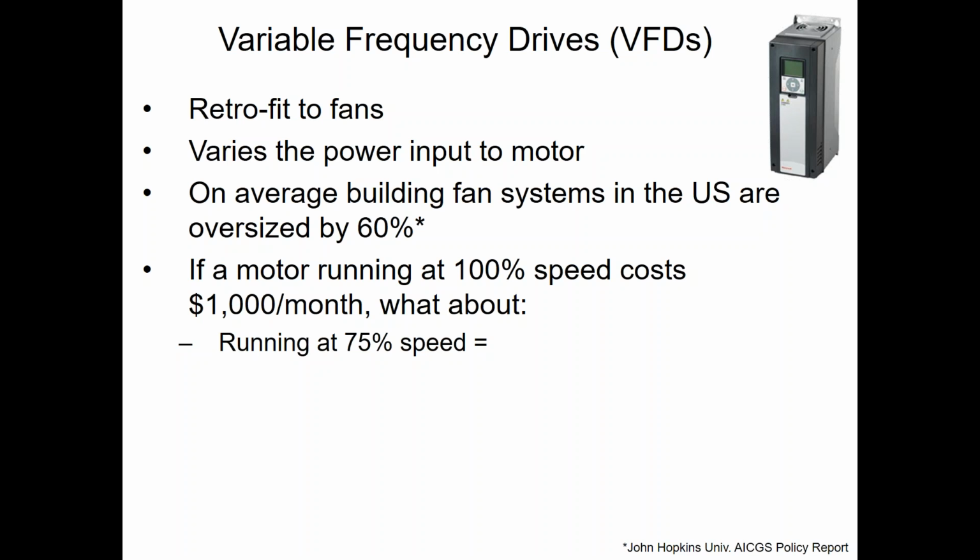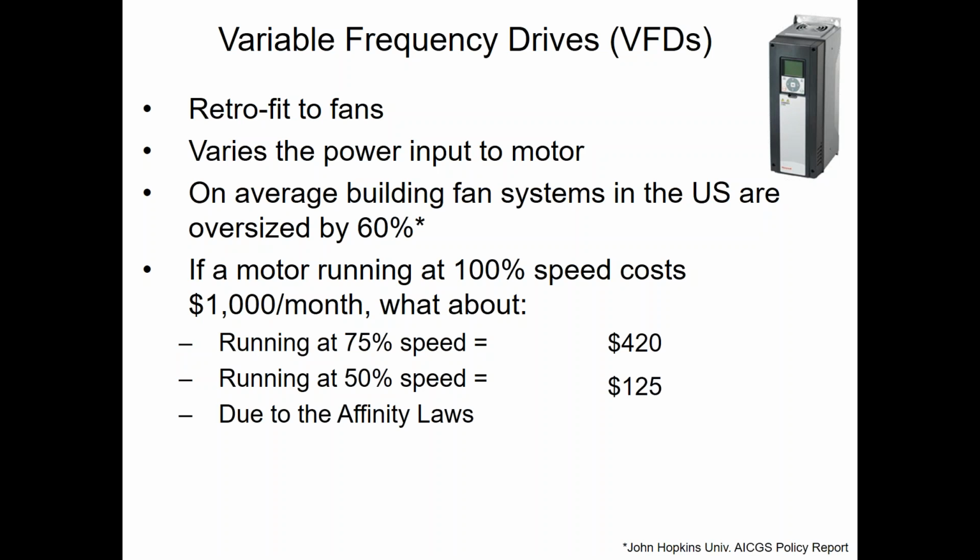If you have a regular fan without a VFD running at full airflow, and let's say it costs you $1,000 a month to run, this is obviously a big fan in this case. If you cut the airflow down to 75%, it only costs you $420. Now your customer is thinking it's going to cost $750, right? Well, it cost me $1,000. If I cut it 25%, it costs me $750, and they might get excited about that, but they'll get really excited when you tell them it's only going to be $400, right? And if they cut their airflow in half, it's down to $125 a month, right?